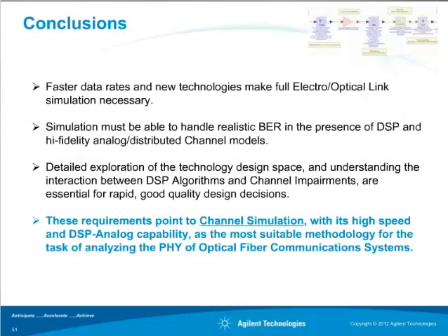So in conclusion, faster and faster data rates and new technologies mean that you really do have to simulate the full electric-optical link to understand it and to get the right characterization of it. A simulation environment for such a thing has to handle realistic bit error rate in the presence of DSP and high-fidelity analog distributed channel models. And you need to be able to interact with the simulation freely to explore the technology design space and understand the interaction, that trade-off between DSP and channel impairments. And you really need to be able to make those rapid, good quality design decisions.